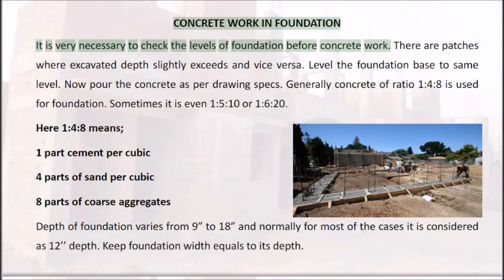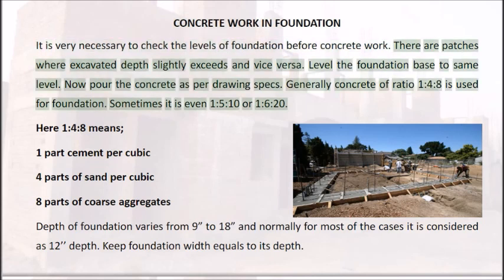Concrete work in foundation. It is very necessary to check the levels of the foundation before concrete work. There are patches where the excavated depth slightly exceeds and vice versa. Level the foundation base to the same level. Now pour the concrete as per drawing specs. Generally, concrete of ratio 1:4:8 is used for foundation.